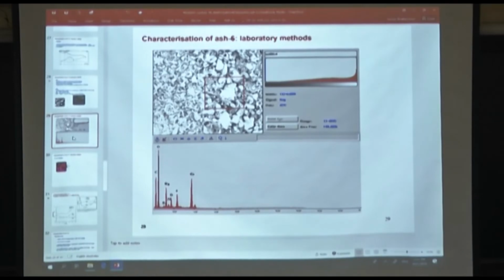If its internal database is not good, if the internal property tables that it uses for the equilibrium constants are not good, then the equilibrium calculations that it performs to give you the products will not be correct either. So it's a matter of time before these databases get more and more developed, and usually the users drive it.